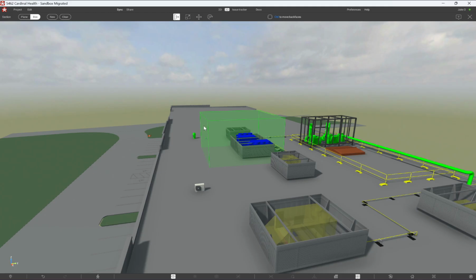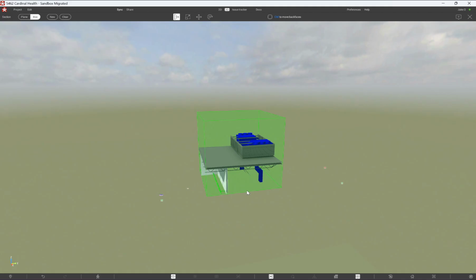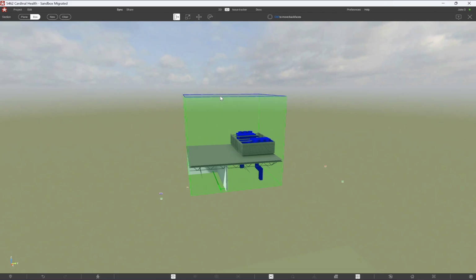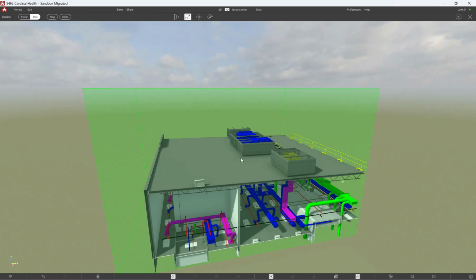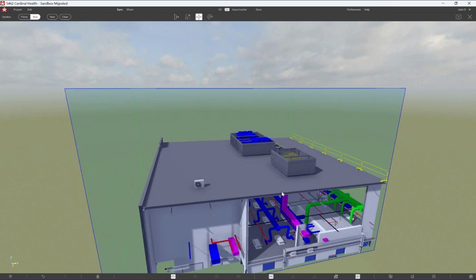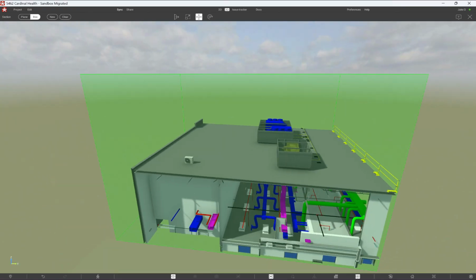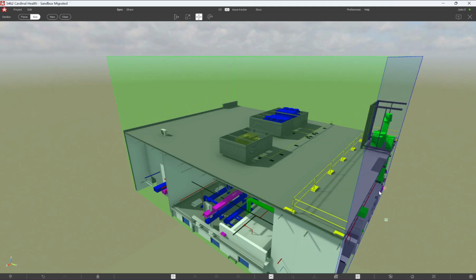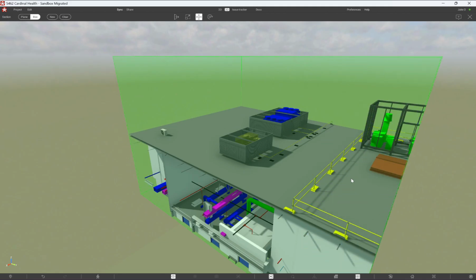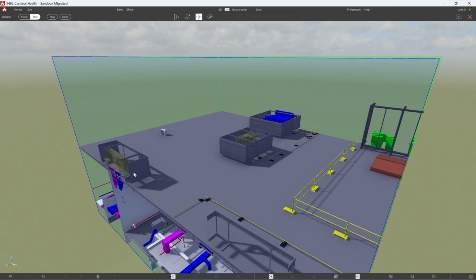So obviously you have your box, and once you click, it'll cut out everything else, but you can drag from any one of these sides and expand or compact the box. Now here you also can just simply have a scale set, so when you pull, it just expands on the entire project, doesn't move. Or this one here just allows you to move the entire box by itself, and it will only show what is inside. So you can see here, drag it this way, it begins cutting off from that end and extending here, or drag it this way as well.